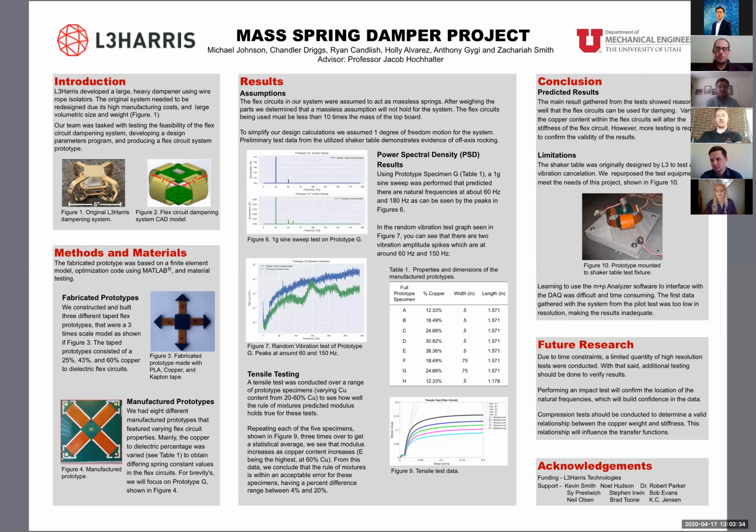From there, we developed 2 orders. Order 1 was to test the Young's modulus theorem, the rule of mixtures, to see whether or not that actually holds true and is valid for our project. We also hoped to do a test on compression to see how well K related to the 2D FEA and Castigliano's theorem, but this was not able to be performed because we ran out of lab space with the virus happening. Order 2 came in, and we created a dynamic response test on a shaker table to actually see how well the natural frequency matched the 1D code for our horizontal component.